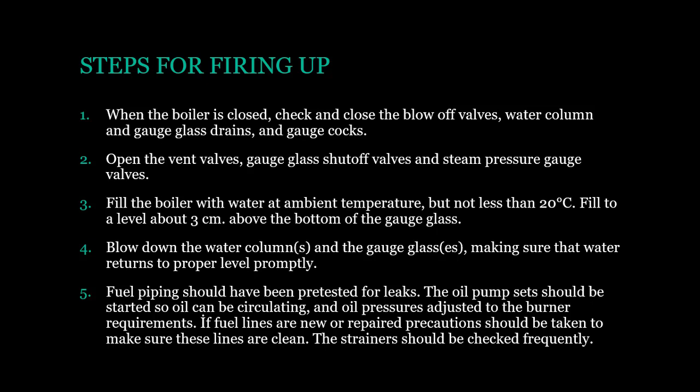Fuel piping should have been pre-tested for leaks. The oil pump sets should be started so oil can be circulating, and oil pressures adjusted to the burner requirements. If fuel lines are new or repaired, precautions should be taken to make sure these lines are clean. The strainers should be checked frequently.